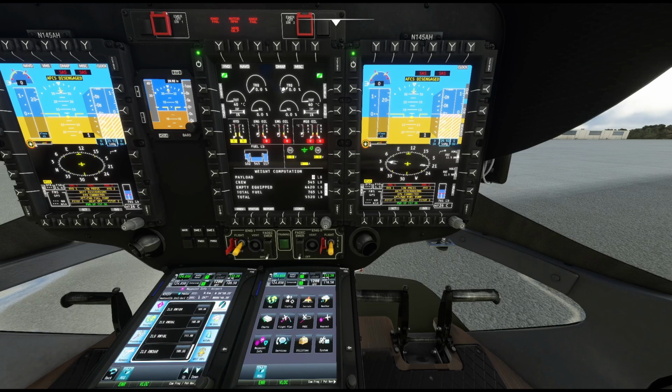All right, these values right here are going to be your old steam gauges, self-explanatory. Torque, TOT, and N1. It's your main 3 that you're going to use to keep your aircraft within parameters. This is all for the left-hand engine, and this is all for the right-hand engine. Now you'll notice we do not have an N2 indication there. The only way to get to that is on the VMS triple tach down here. These are your N2 indications for each engine.